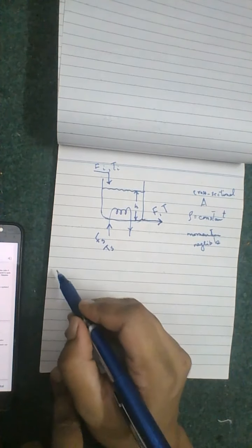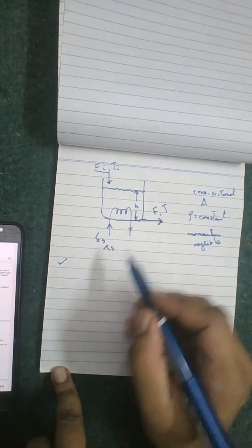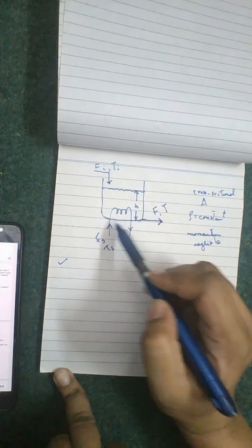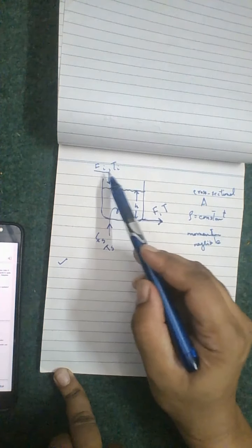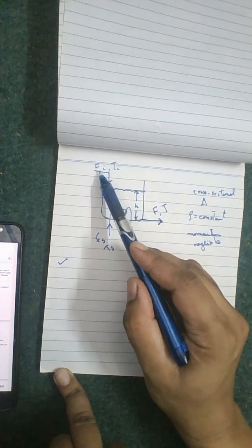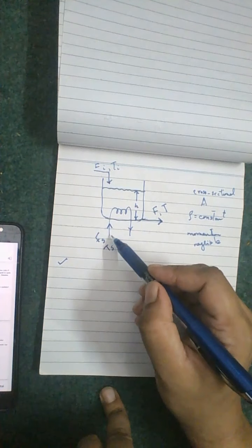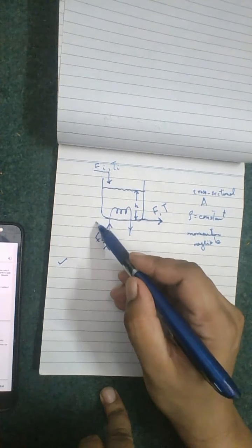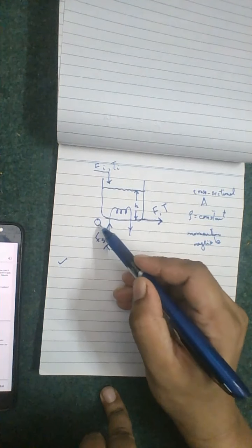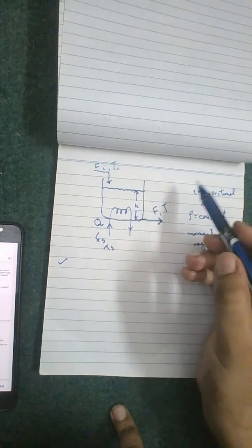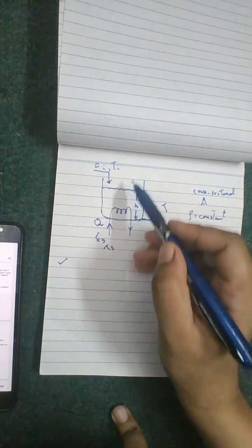So our purpose is to construct the flow diagram. We have constructed the flow diagram. We have constructed the tank, the inlet having a flow rate Fi and Ti, the outlet flow rate F and T, and a steam entering the system, giving the heat Q to the system so that the liquid inside the tank can be heated to a specific temperature.